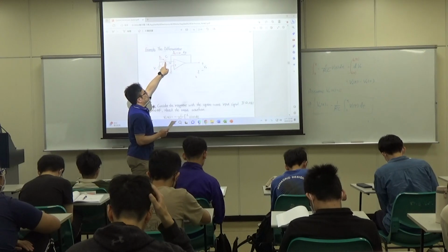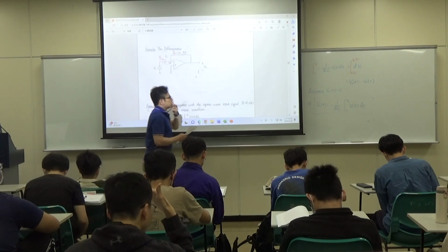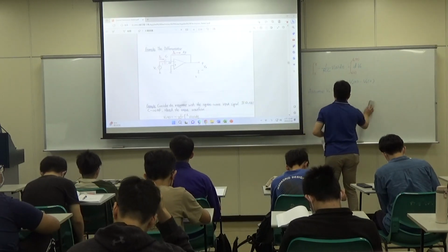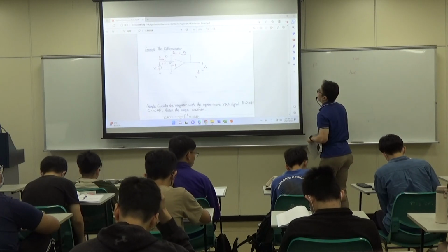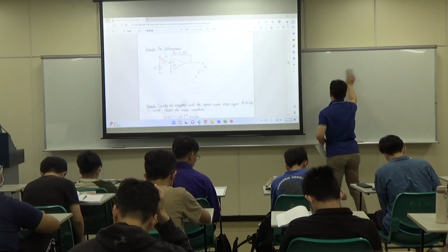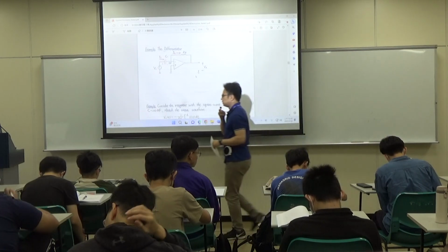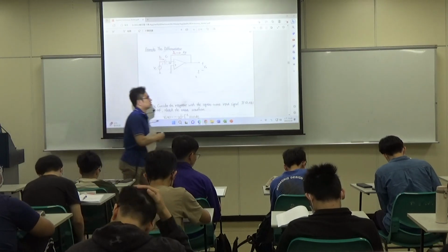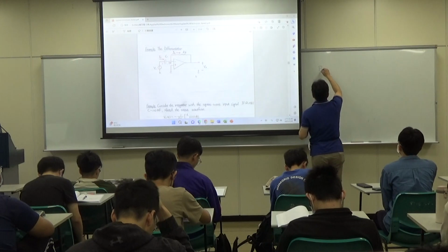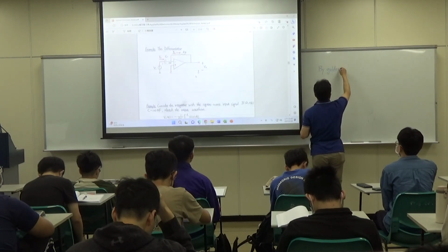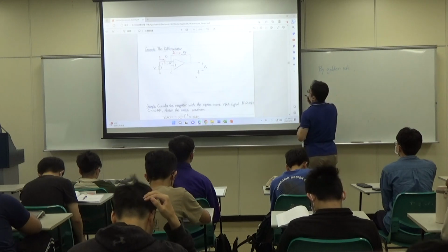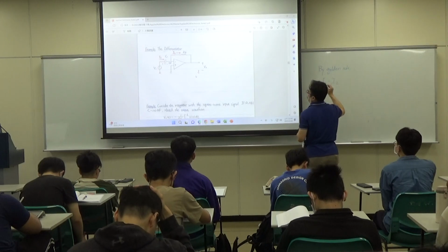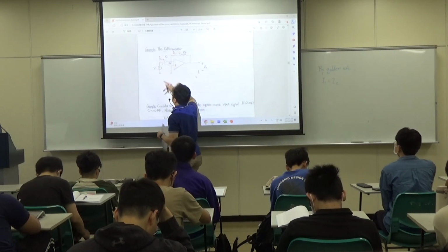Okay, the same thing: replace the RI, the input resistance, by a capacitor. So by KCL, yes, we apply the golden rule again. We have I1 equals I2. So by the golden rule, we know I1 equals I2, and this is zero volts, right, by the golden rule.